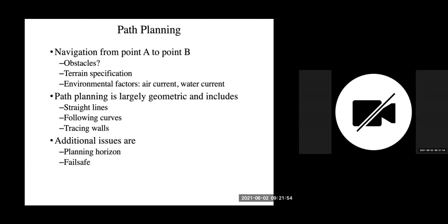Path planning is one important aspect to talk about before actually implementing the algorithm. Path planning talks about what kind of path we will select. It does not mean that we will exactly follow the path; path planning is at a little bit higher level, and we also have motion planning below that. Motion planning talks about exactly what kind of motion the drone, the aircraft or the robot should take to be able to follow the path.